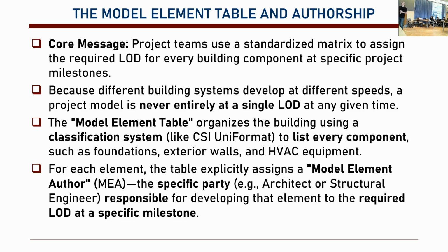So for that, you create a model element table and you use a classification system like CSI uniformat, okay? For every component, like foundations, exterior walls, HVAC equipment. Basically, this table assigns a model element author.